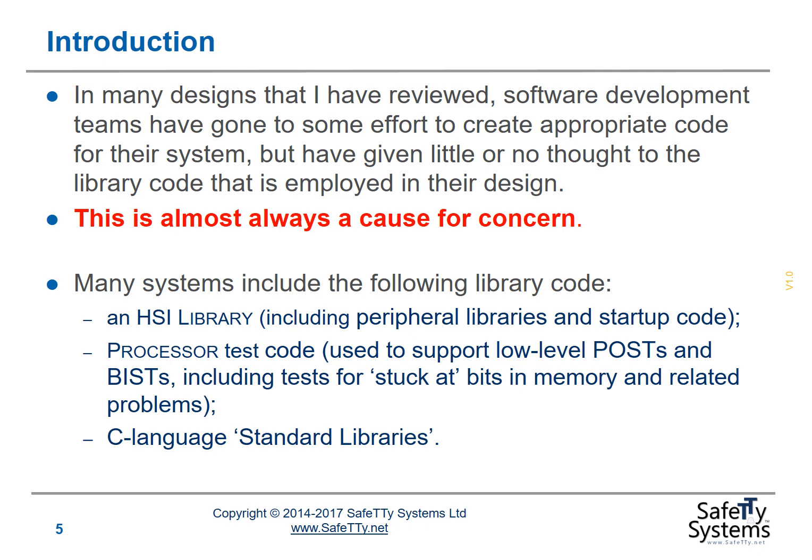Many systems include the following library code: the HSI library, including peripheral libraries and startup code that I've just talked about; the processor test code used to support low-level power-on self-tests and built-in self-tests, including tests for stuck-at bits in memory and related problems. We'll look at the processor test code in later parts of this course. The final part of the library code that's used in some designs is the C language standard libraries.